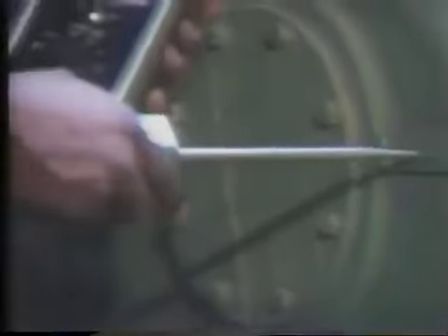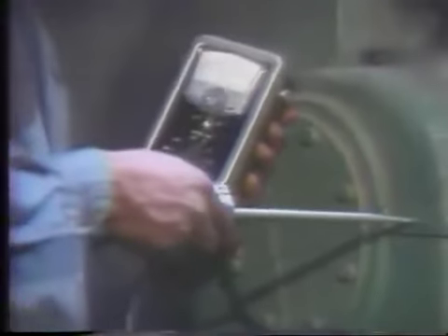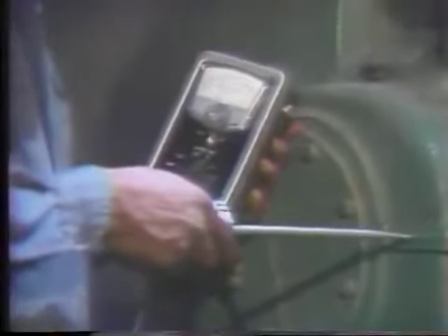Temperature isn't the only thing that an operator must check on a bearing. You also need to check for vibrations and listen for unusual sounds. Unusual sounds and excessive vibration can be an indication that the bearing is not functioning properly. An instrument used to check vibration is called a vibrometer. Its probe is placed on the bearing housing, and the amount of vibration is read directly from the meter.